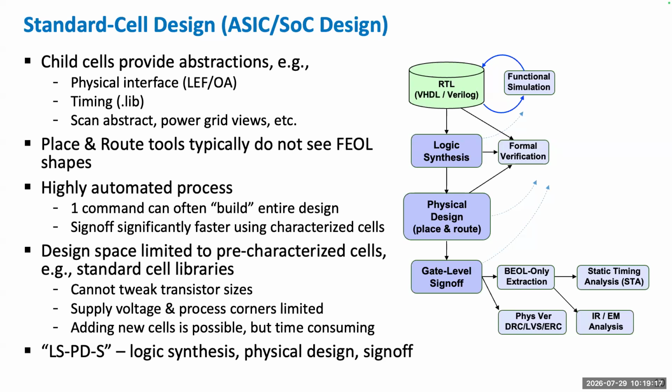So typically you have pre-characterized, let's say, transistors and gates and front-end of line. So you're only doing a back-end of line extraction. That's going to speed things up significantly. Now, one line command is good for, let's say, an easier design, but then the crux of it, okay, what do you do when that doesn't provide the quality you want? That's what we'll address. But the key thing is the build pipeline. You can go through a trial with very little human effort, still maybe a lot of compute time, perhaps days to weeks for a full pass, but at the same time, your effort is now significantly reduced.